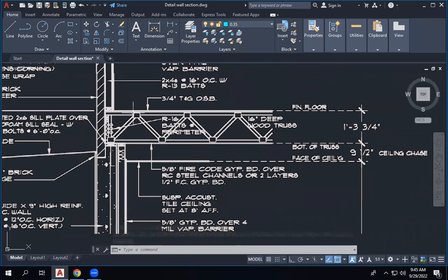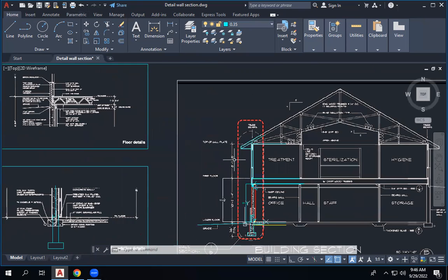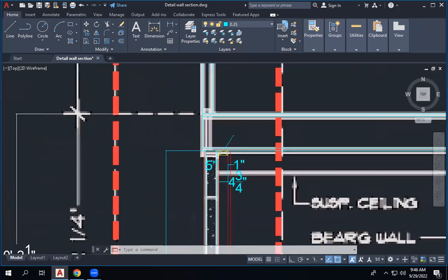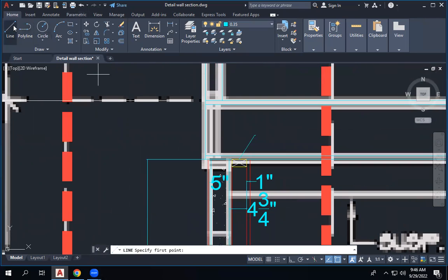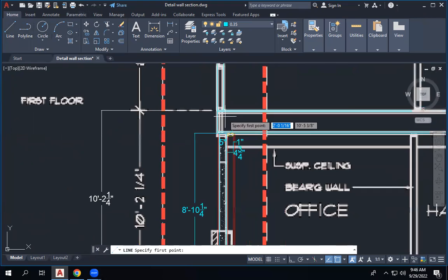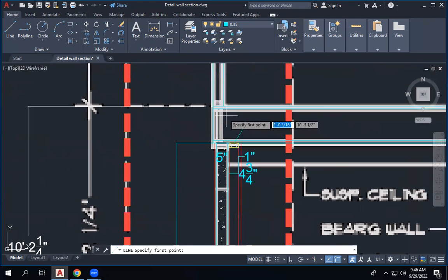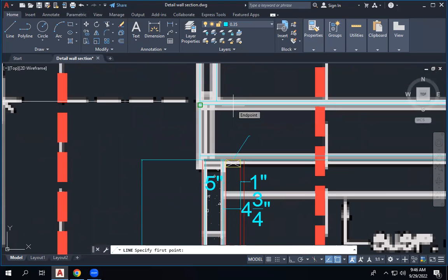And you have this plate. The truss is made like this. They will cut the steel sections into these small pieces, and they weld them to this plate. And the plate is welded to the main section. The truss should stop here. Yeah, these 2 lines by 1 inch. 1 inch. Yeah.